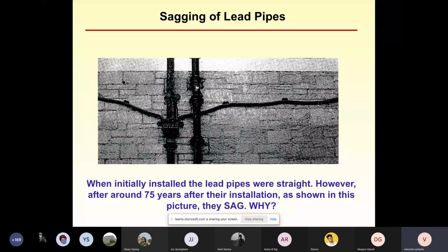Two parts are being clamped together using bolts. The bolts are initially tightened to ensure that these two parts press against one another and that there is no separation between the two. But then over a period of time, the bolts can actually elongate because they are under stress. You are compressing the plates and the bolts will be in tension. So the bolts can extend in length, thereby releasing the mean force which we had initially generated. That is of great concern.